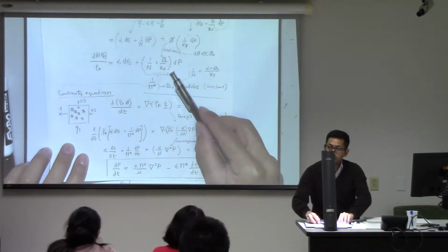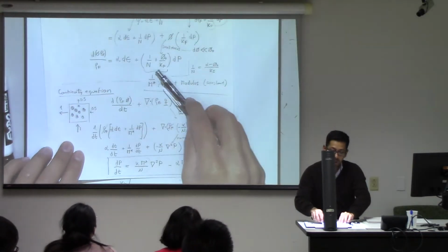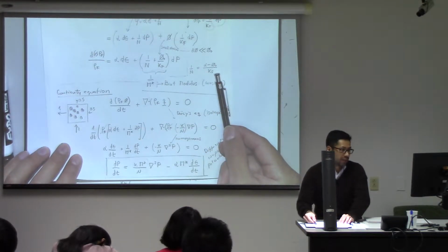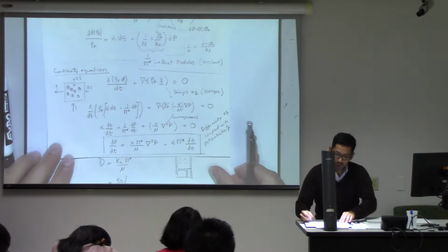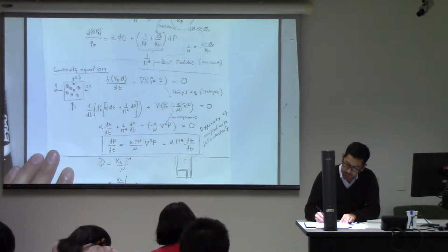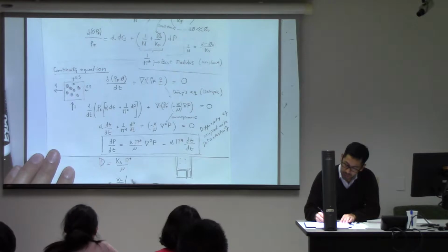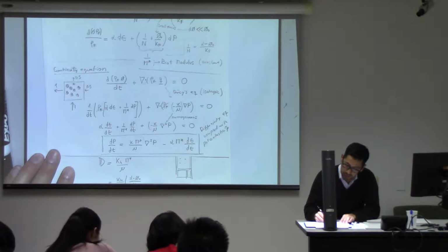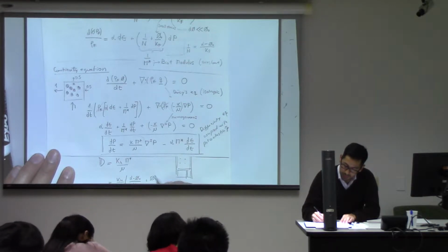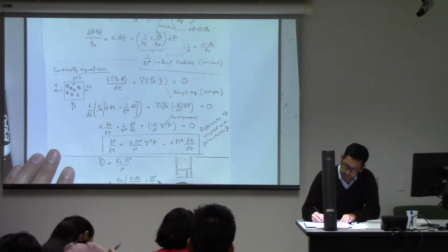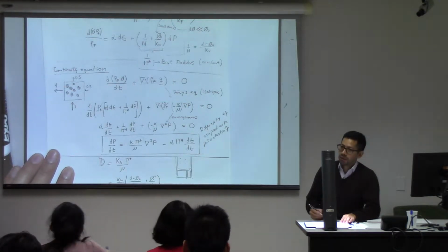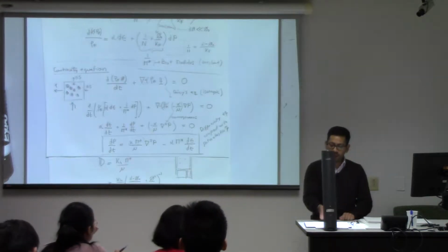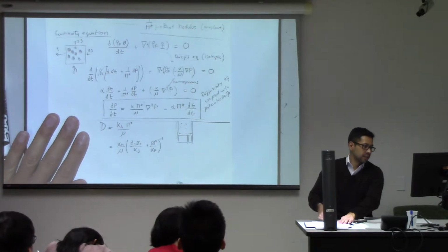That was M, right? And that M, if I replace the value of 1 over N, is that. And if I do a little bit more math, I can calculate this as alpha minus porosity divided by Ks plus porosity divided by Kf. And this is what I missed in my email. Sorry about that. So it's the inverse of that.